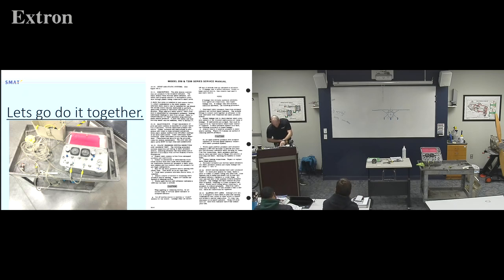In 1 minute, the leakage should not exceed 10 knots is what it's saying. So basically, this goes on here, I roll this up to 150, and we wait. If it doesn't get below 140, I go, oh, good, the pitot system's good. Now I want to test the static system. I'm going to plug it into the static. I'm going to draw a vacuum up to 1,000, plug it off, and wait. I believe that one was the 1 minute, and it shouldn't go less than 100. So that's how we can do it, the cheap version.